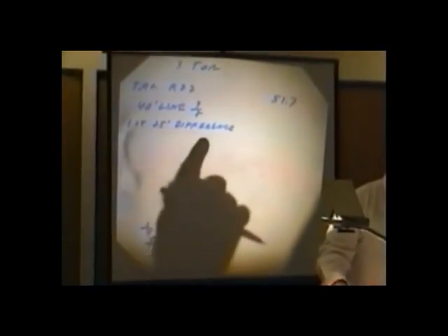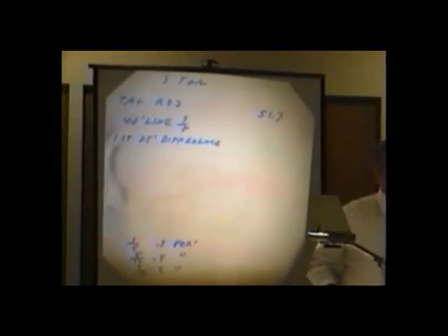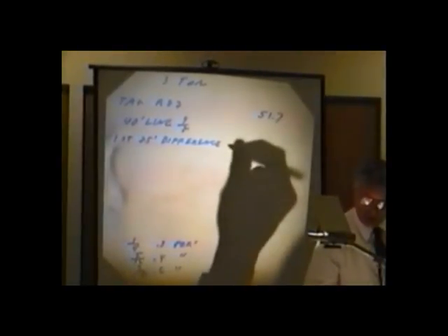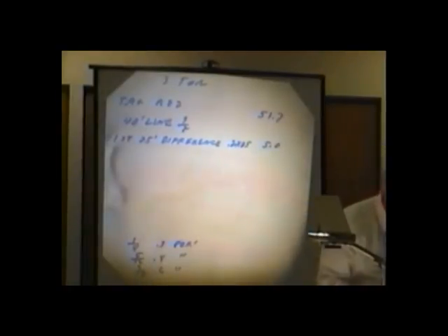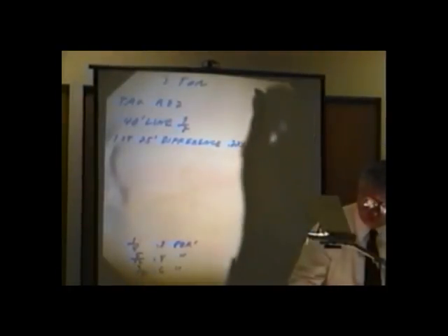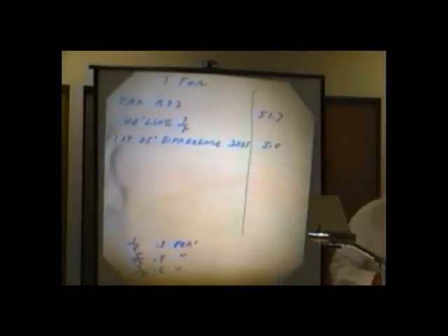So the first 25 foot, the difference, because you're using a bigger line, is 3/8, and we know that the difference between 5/16 and 3/8 is 2/10. So I want to take 0.2 times the first 25 feet, and that would equal 5 ounces. Is that okay? Try and draw a line here so we don't get confused. Okay? So now I have to add already 5 ounces.